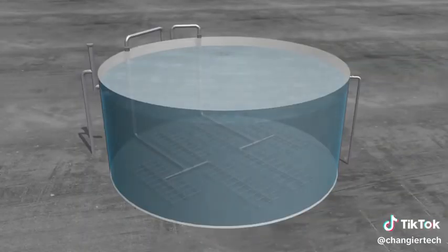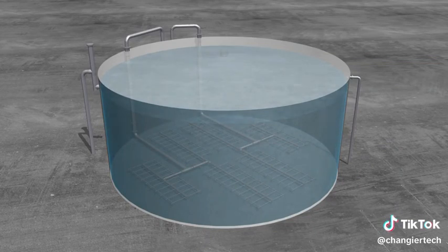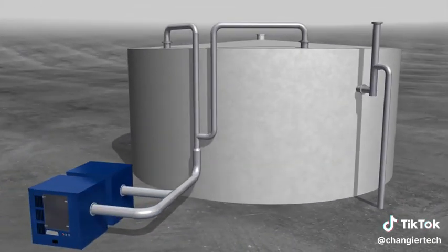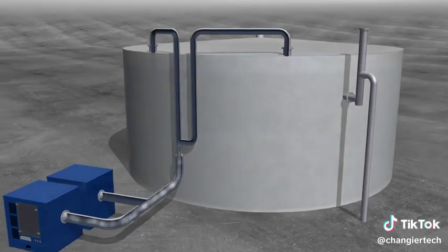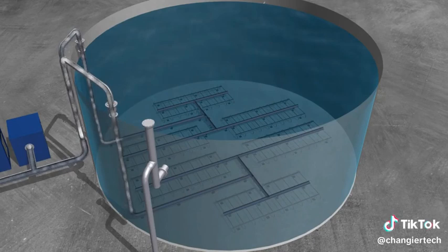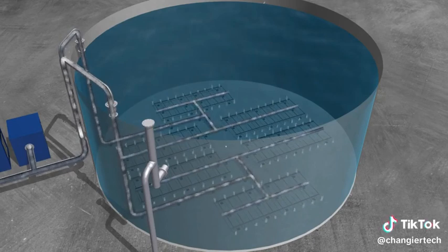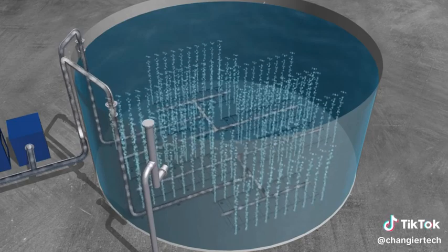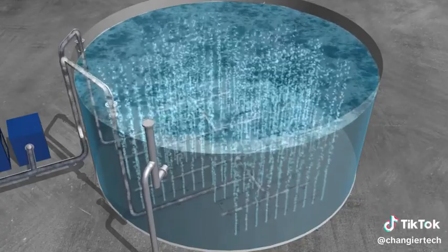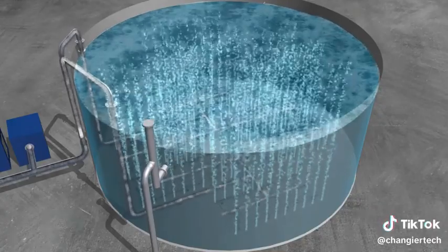An MBBR for BOD and/or COD removal or nitrification is an aerobic system, meaning oxygen is introduced into the reactor to allow bacteria growth. Oxygen is brought into the tank by having blowers send air through stainless steel aeration manifolds. The aeration manifolds are strategically placed inside the tank to have even coverage throughout the entire volume of the reactor, and to provide the necessary mixing for maximum treatment during the reactor's retention time.